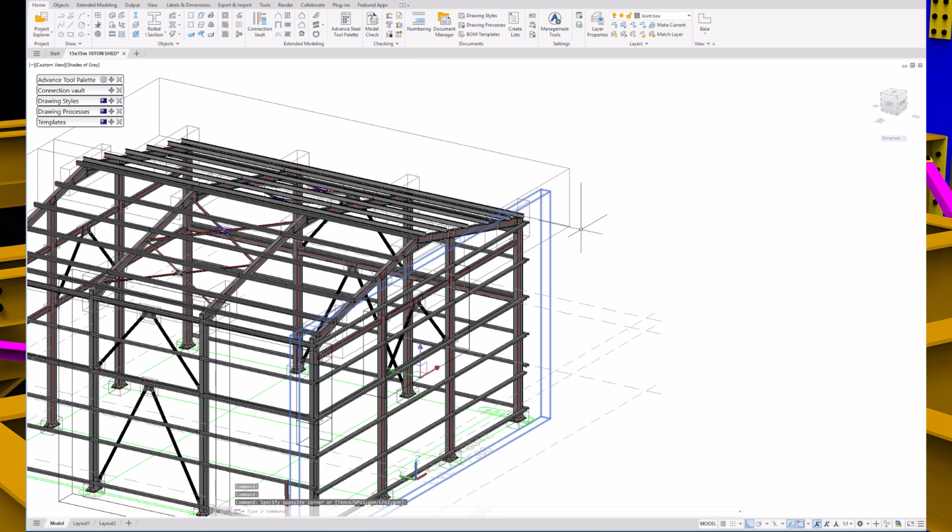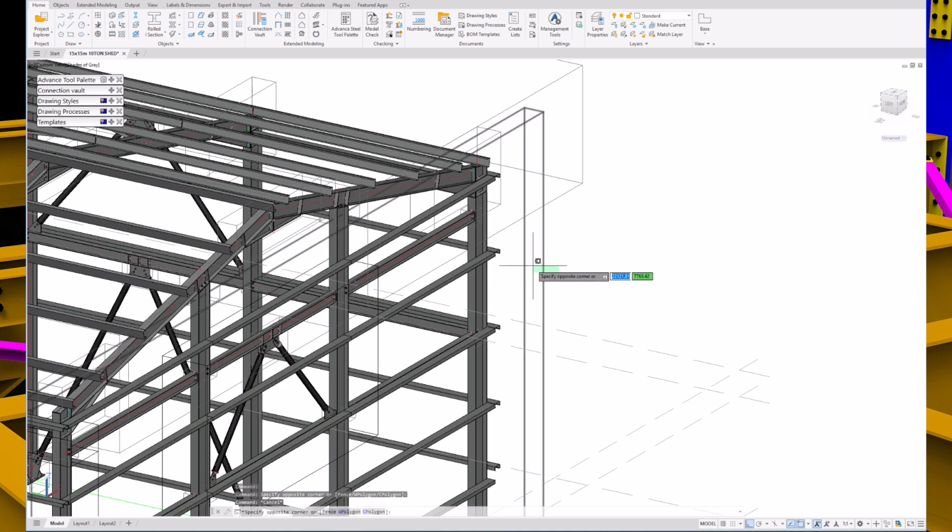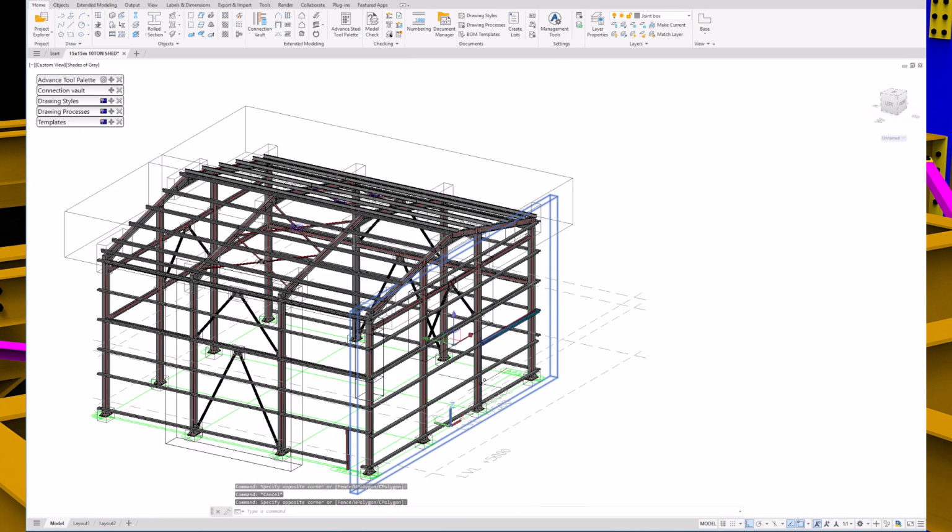Let me just close this. I'm going to delete the intelligent box. Why? Because this is where we need to get our opening. And we cannot just delete anything that came with the intelligent box. Why? Because it would delete everything that came with the intelligent box.